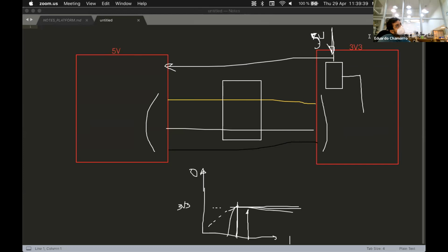And the other one is current, because here you might have a power supply that gives you, I don't know, 200 milliamps. This LDO is rated at 100 milliamps, because here you have whatever it is at a 50. So you have some safety margin. So it means that more or less here you have at maximum 150, but to be safe, let's say 100, because this could change and there could be peaks or whatever. So then you have here a limitation of, again, 100 milliamps of usage, which is fine.